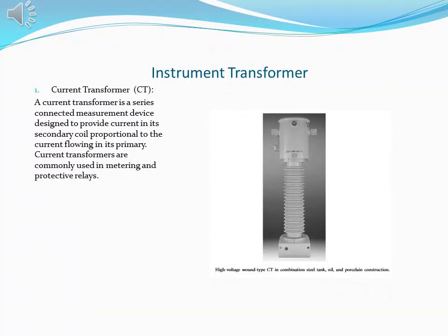Current transformers are used to step down the current levels so that ammeters, current coils of other instruments and relays need not be connected directly to the high-power operating circuit. Hence, all these instruments are isolated from the high-power circuit. A current transformer consists of separate primary and secondary windings. The primary consists of one or a few turns of heavy wire wound on a laminated core. This winding is connected in series with one of the power lines. In some CTs, the line conductor or wire itself serves